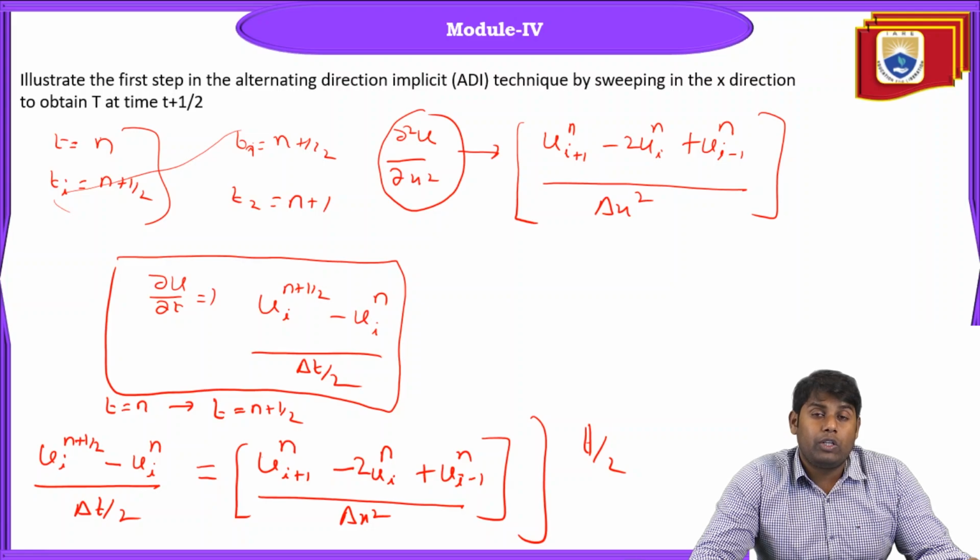Initially we use the explicit method to predict the value, then we switch the other time step to implicit, which is called the corrector. The predicted value from the first half is taken to the second half as an input and we correct it, and for a given iteration we solve sub-iterations such that we get an accurate value. This is the main motto of ADI.